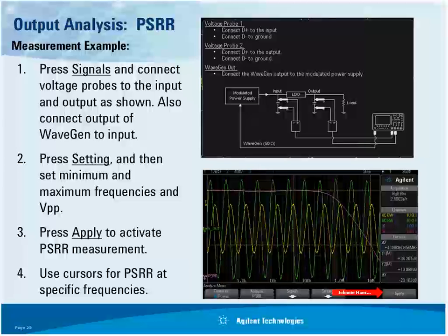It's not as fast as a network analyzer, but this is what I call a poor man's network analyzer. Now, it's not as good as a network analyzer. The scope can measure to about 50 dB. Now, the type of probes it's going to require, typically the input is being modulated. In this case, this is the yellow waveform, a relatively high-level signal. It may be a half a volt peak to peak. You can just use one of the standard probes that ship with a scope.